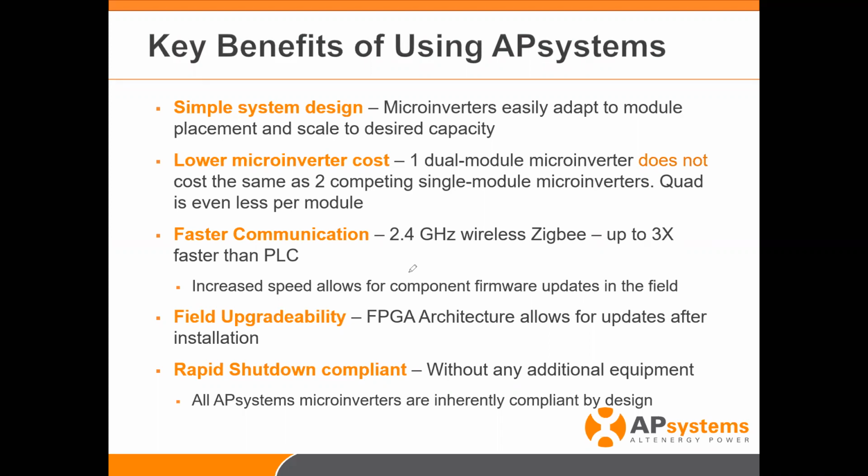And I also want to add on top of that. We've had some areas of the country where, when we do an installation, we see some interesting anomalies in the power grid in a particular area, depending on the utility and the region and the distance from the utility. So in some cases we've had to change some of those microinverter parameters to accommodate what the grid conditions are like in those areas.